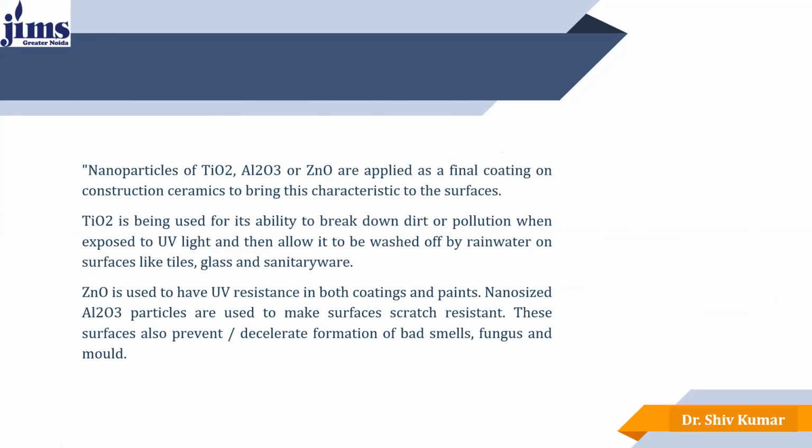Nanoparticles of TiO2, titanium dioxide, Al2O3, aluminum oxide, and zinc oxide are applied as a final coating on construction ceramics to bring this characteristic to the surface. So TiO2 is considered a self-cleaning material. It can also remove stains on the surface of the wall through a photocatalytic reaction.